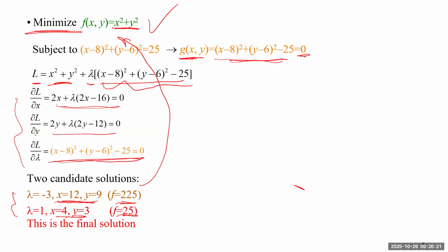It's solved. We don't utilize any knowledge about the geometry, and we can solve this problem. So you can apply this approach to any more complex cost functions and any number of equality constraints. You just go ahead and try this step. If the dimension is not extremely high, the candidate solutions may not be many, so you just check their cost function one by one to see which one is the smallest. Definitely it may take some effort to solve those nonlinear equations. You may want to utilize the Gauss method, Newton-Raphson method. Yeah, so that's it. That's a technique we're going to use in our economic dispatch.